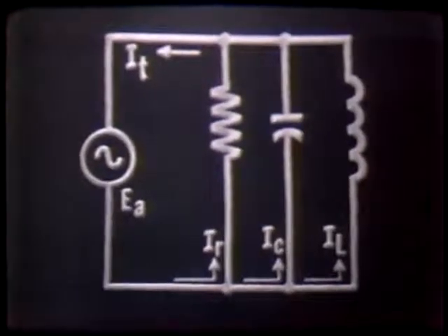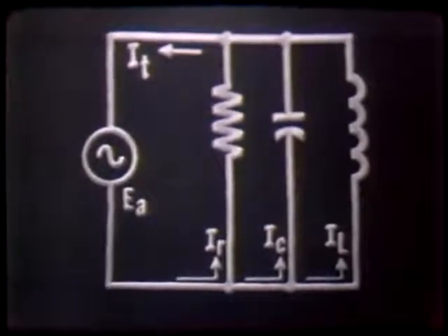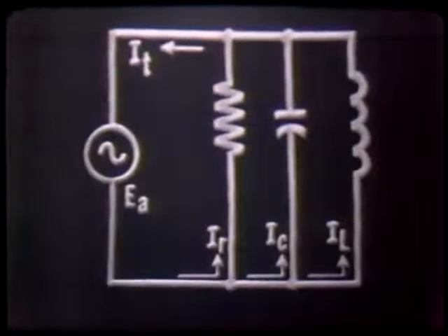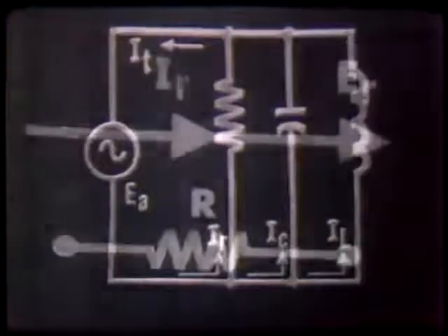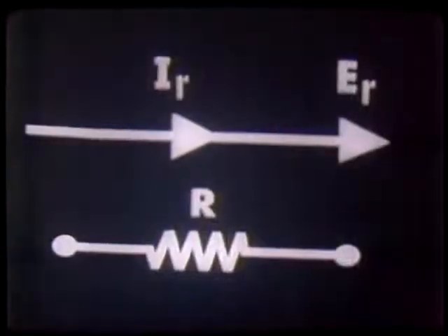The voltage across and the current through any pure resistive component is always in phase and is vectorially represented this way: IR in phase with ER. Note ER represented here would be the same as the applied voltage since we do have a parallel circuit.